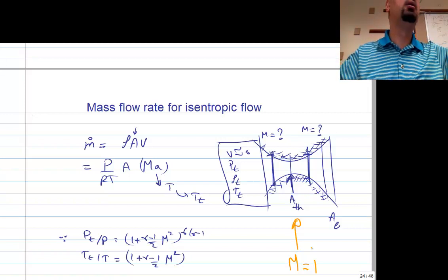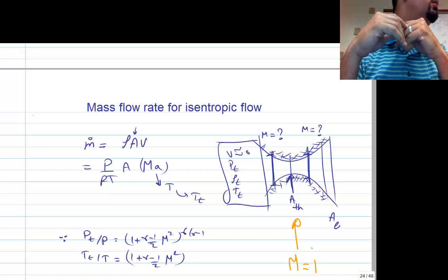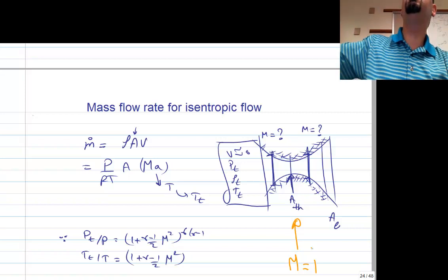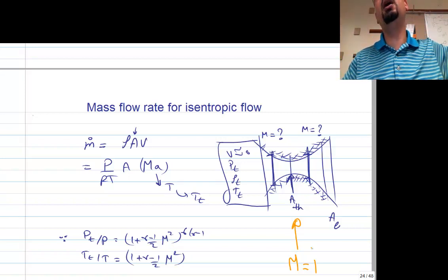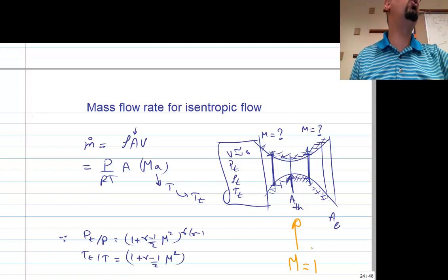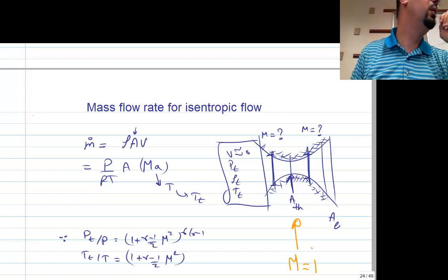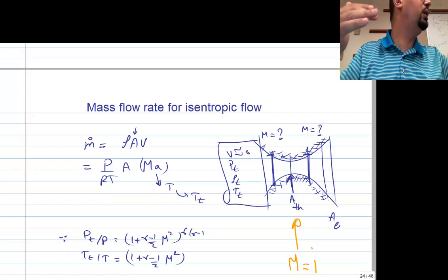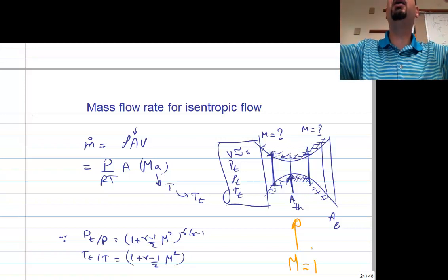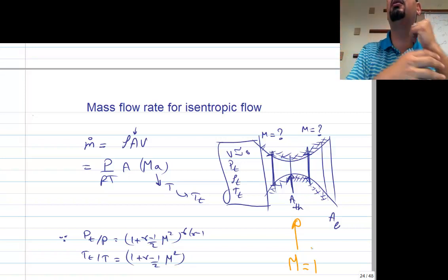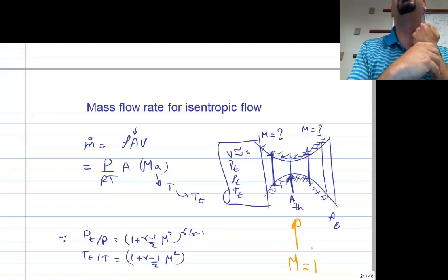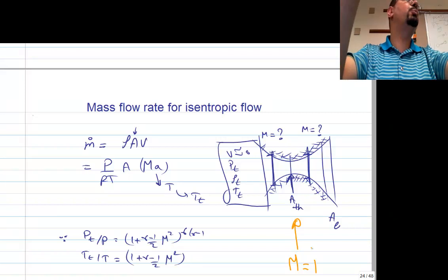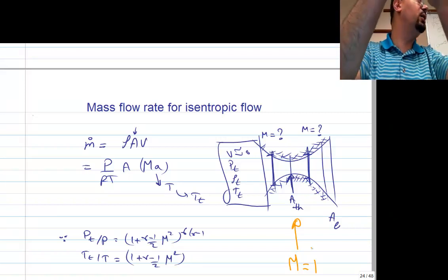P atmosphere, P atmosphere. What's the Mach number in the nozzle throat? There is no flow. Let me just increase the pressure in the tank a little bit. Let me put 1 Pascal. You think the flow suddenly will jump supersonic in the middle? It takes a really big difference between the inlet and outlet to get supersonic. So what I'm saying is that not every single convergent divergent nozzle will have supersonic flow at the exit and sonic at the throat,